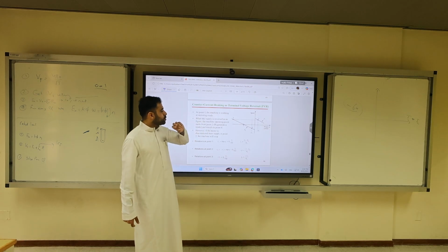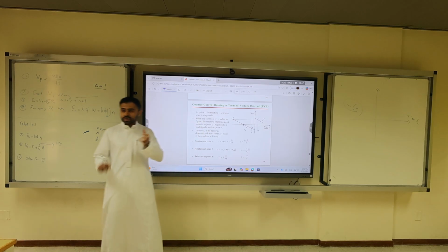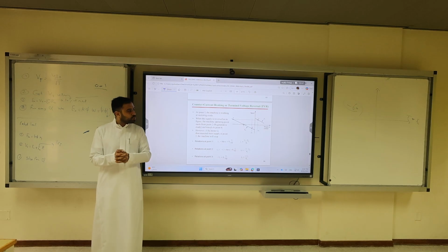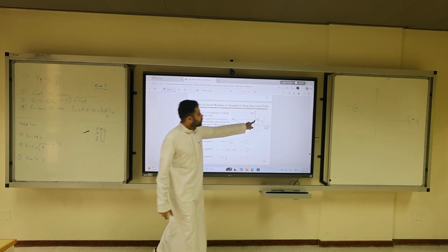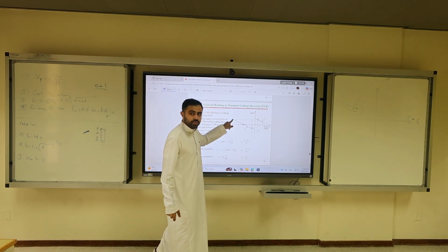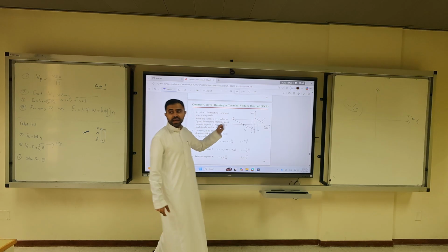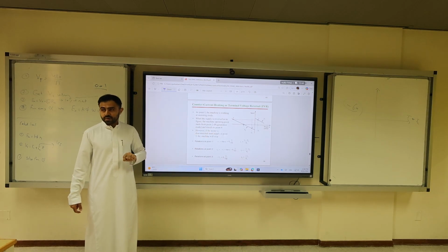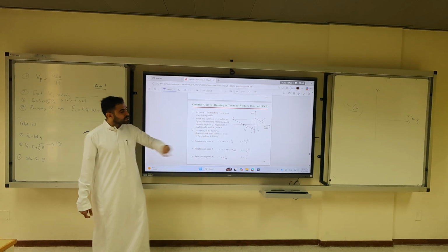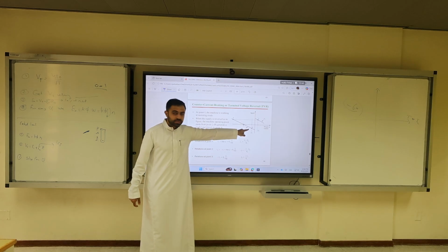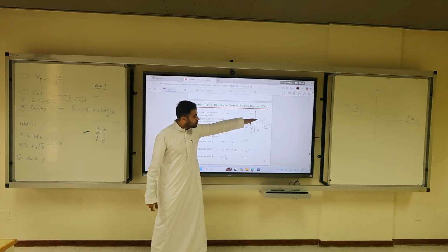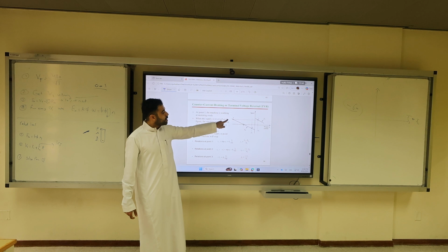Now you reverse the direction, reverse the supply. What will happen? You have to jump to point number 2. You maintain the speed. However, the current becomes extremely negative, very big negative. Can you change the speed directly to 3 or 4? No, because you have to go through the process.